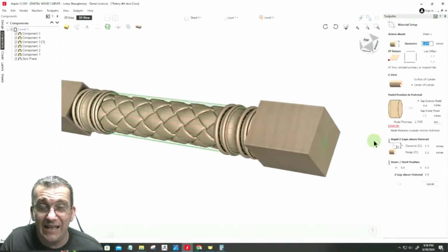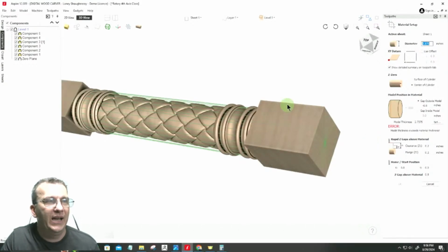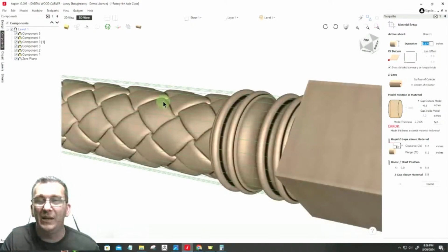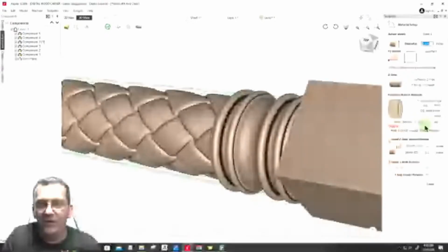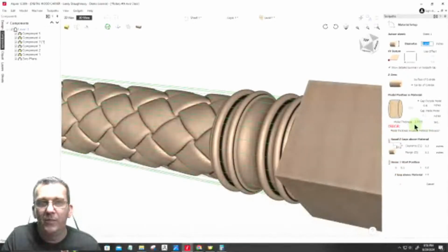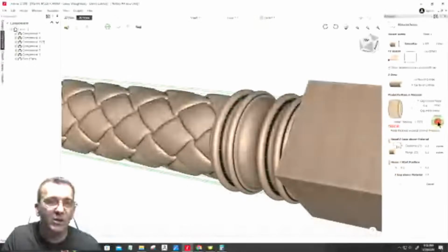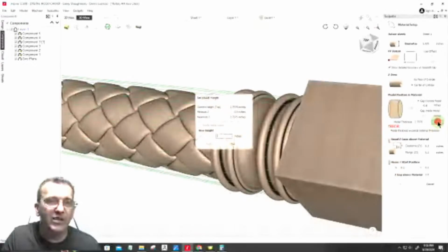Now, what has exceeded the part, ladies and gentlemen, on that thickness is the corners. The corners are much taller. You can see the green lines represent the boundary of my 3 7/8 piece, so this part is much bigger. My model thickness should be 1.9375, but it's 2.7375. So I should be able to go right into my model thickness and change the overall height,